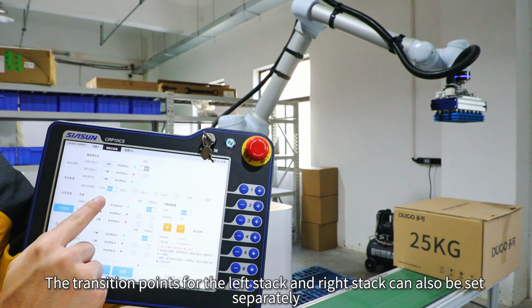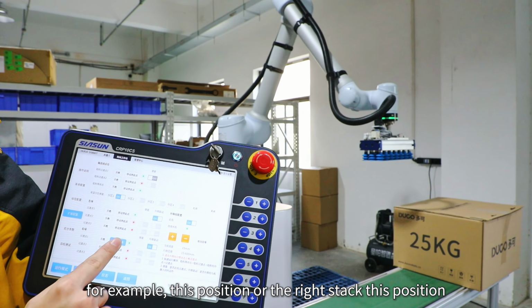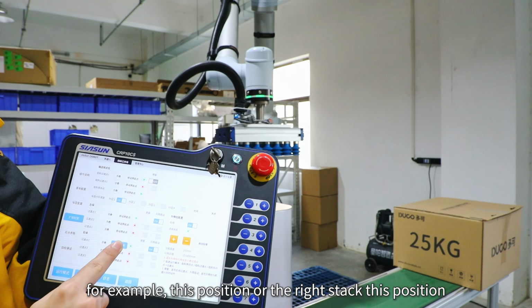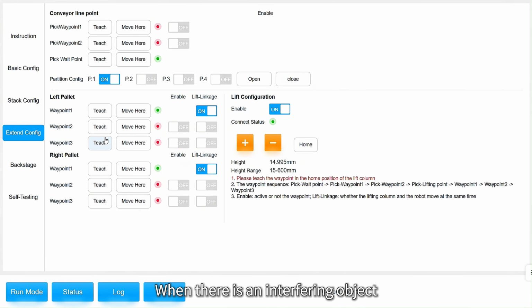The transition points for the left stack and right stack can also be set separately. For example, this position or the right stack this position. When there is an interfering object at a certain position on the pallet, you can add 2 transition points to bypass it, but usually these 2 points do not need to be used. After setting this point, if you do not turn on the enable, it is ineffective.